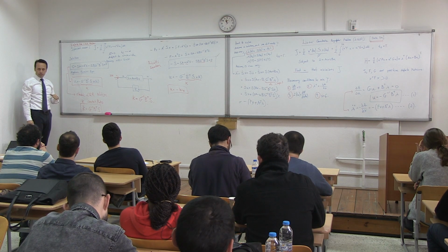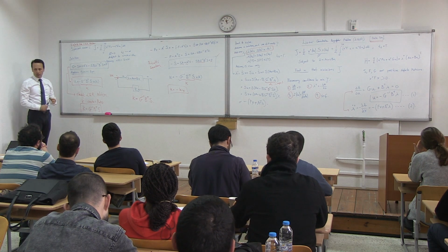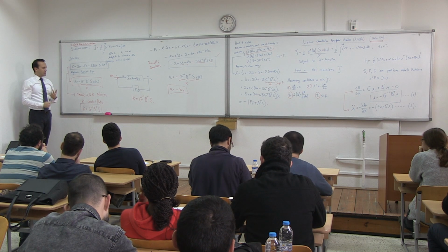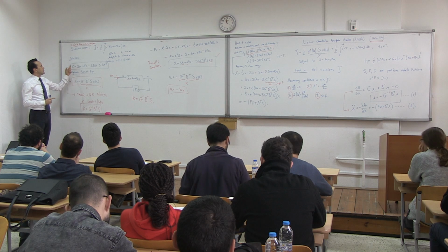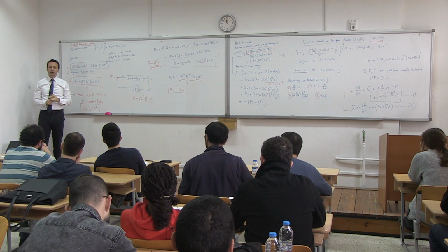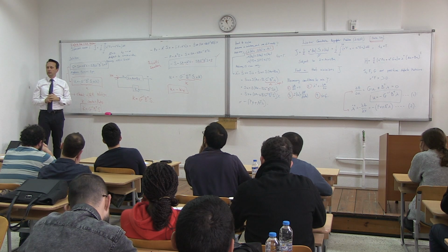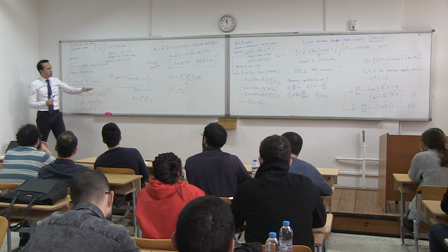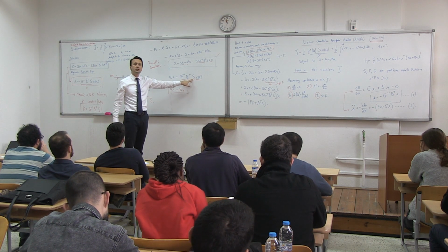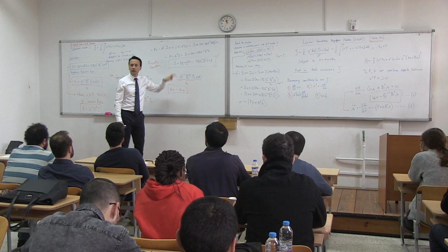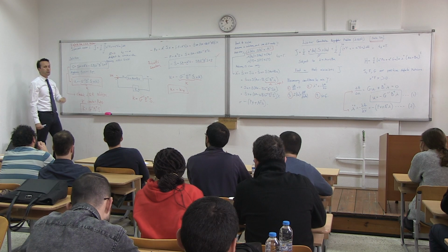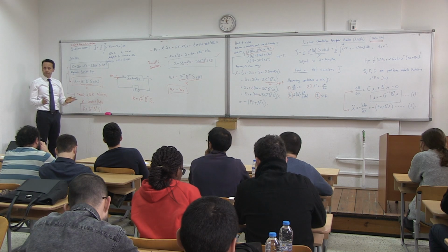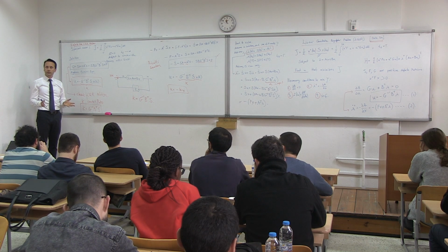So this is an algebraic equation. And this is called the algebraic Riccati equation. Okay? So don't forget Riccati equation, algebraic Riccati equation, LQR solution, and where this is coming from. Is that okay? Does it make sense? And this one gives you a k value that is changing with time, right? S is changing. Here S is not changing because this is now an algebraic equation. You will get a fixed k number. That's fine so far? Any questions?